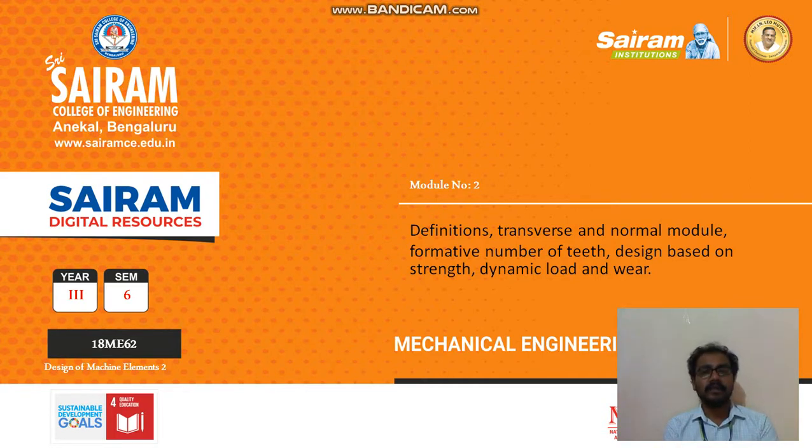If you want to understand helical gears in a better way, we need to compare them with the previous one, that is the spur gear, because the procedure I will be following to understand the helical gear is based on spur gears only. We know a spur gear is where the two gears, pinion and gear, have shaft axes that are parallel, or even coplanar, and the teeth are straight and intersect with each other. That is the spur gear.